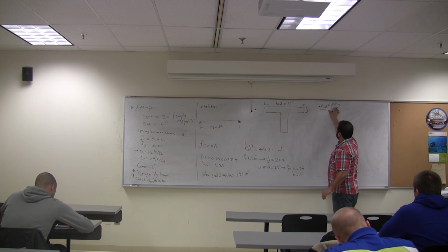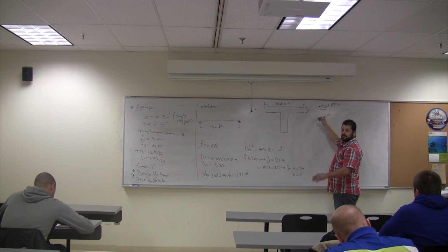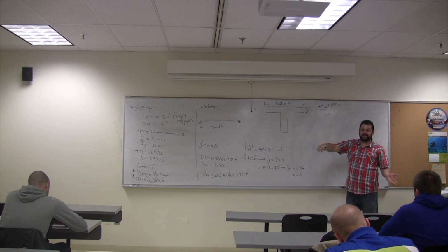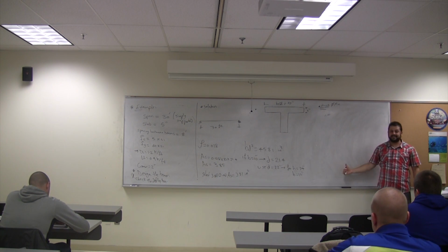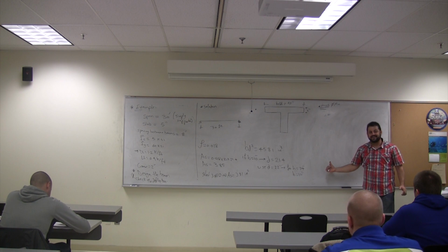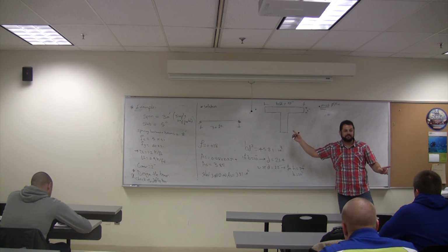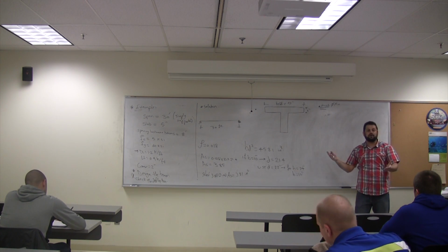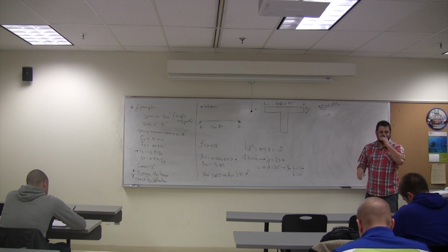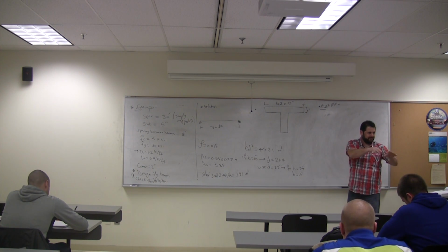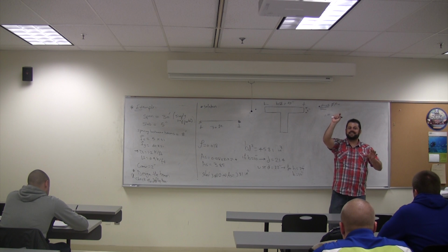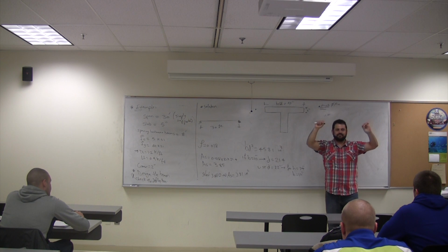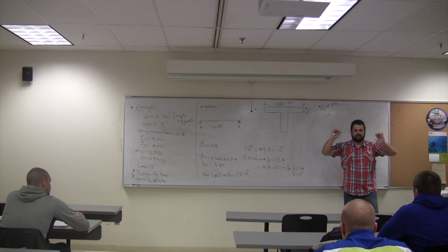First of all, what do we check, guys? Is it within the flange or not within the flange? So rectangular analysis or non-rectangular analysis. By the way, the R method I did here is for rectangular analysis. Be careful. It doesn't work if the analysis is a T-beam. If the analysis is a T-beam analysis, the R method I used here doesn't work. But most of the time it works. That's why, if they want to give you a T-beam example in the book, or I give you, usually they give you the flange is 3 inch and f'c is 3 ksi. In a rare situation you will have a T-beam analysis requirement.